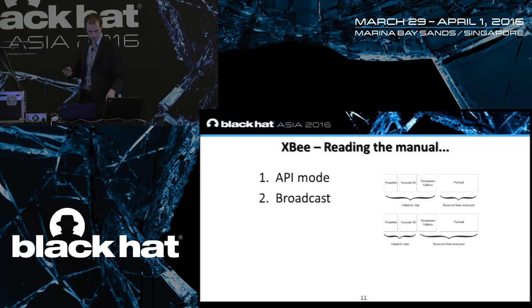So you send with one of those chips here, first you switch to API mode, then you send a broadcast out to the network, you receive acknowledgements back, one from the UAV, one from the telemetry box, you extract the sender's addresses because the address of the sender is inside of that packet, right, the acknowledgement packet. You extract those addresses, and then you know the participants within the network. So you know who the UAV is, which address it has, and you know the telemetry box.